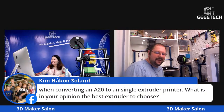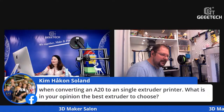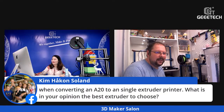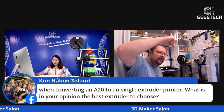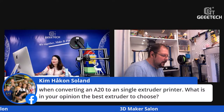It depends. I can't say, okay, this is the best filament or this is the best extruder out there. You must see what use case you have for your printer. Do you like to print more TPU, very flexible materials? Then you would need a direct extruder, which drives the filament directly from the gears into the nozzle. If you like to print faster, or